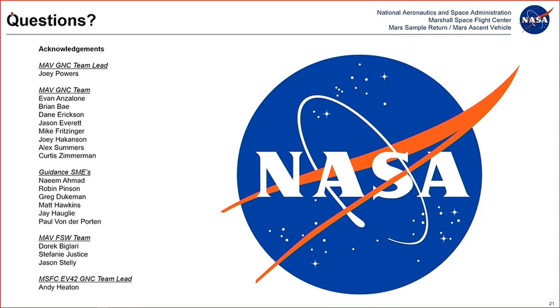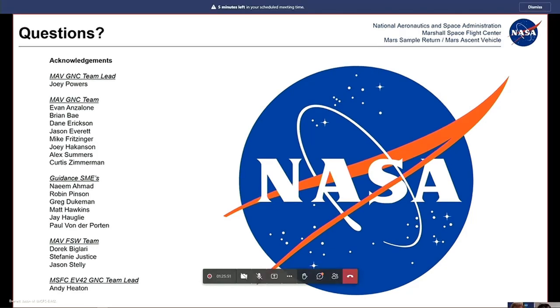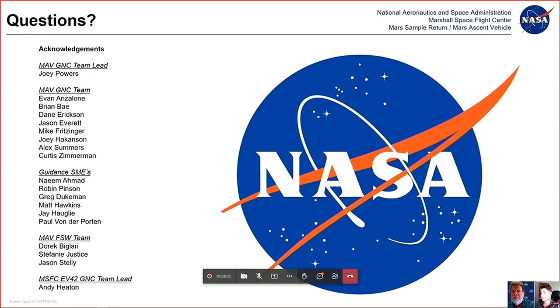The next question: during the burn stage, will it be active as you exit the atmosphere, or will the burn stage conclude prior to that and the rocket will coast out of the atmosphere? Yeah, that's a good question. So the current vehicle design, and it changes every vehicle design, does have us still being in somewhat appreciable atmosphere by first stage cutoff. So by the time our first stage solid rocket motor is depleted, we are still seeing some significant aerodynamic forces on the vehicle. But that being said, it bleeds off very quickly after first stage burnout, and then most of the coast is outside of appreciable atmosphere. Okay. Very good. Thank you.